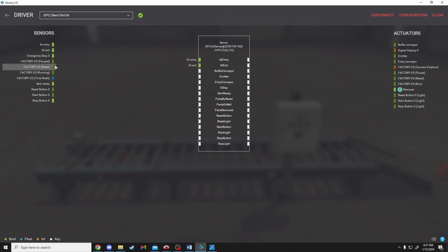Exit. Just start plugging them in. As long as we don't add new variables, we can just go ahead and update our ladder logic as much as we want without having to replug these in or add any new variables. We can just update our ladder logic and try stuff. As long as you're not adding new variables, you won't have to redo the symbol configuration and all that stuff. What do we have here?